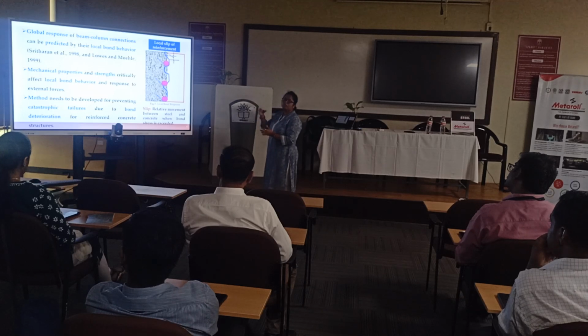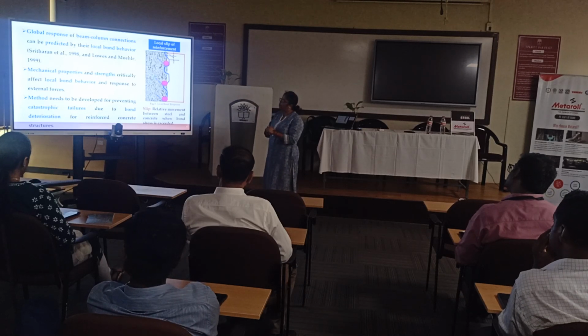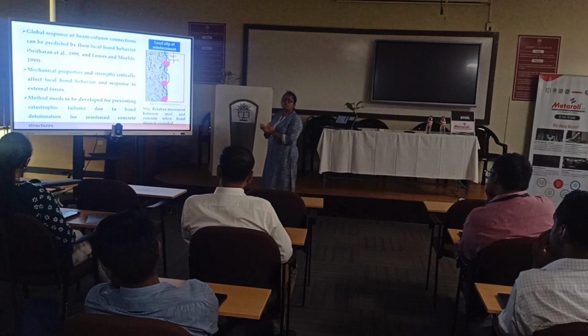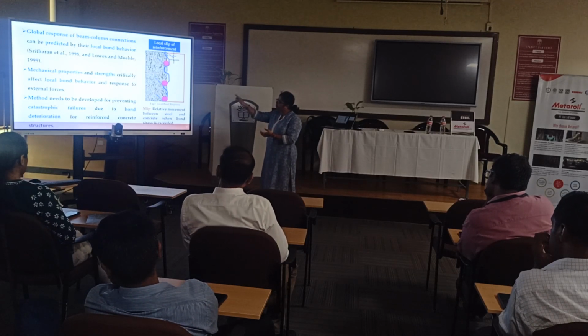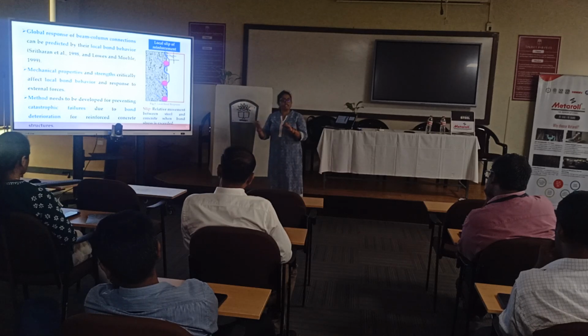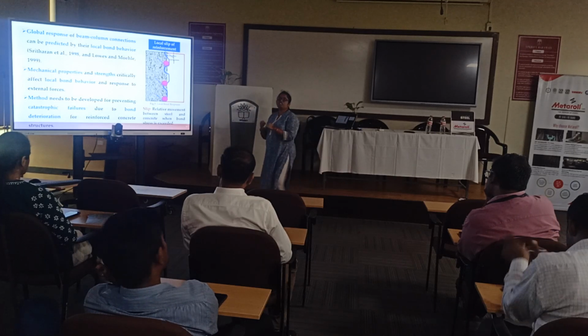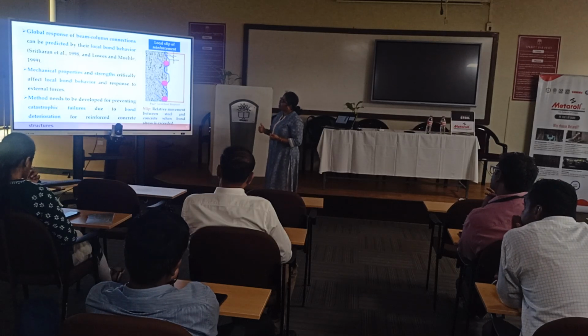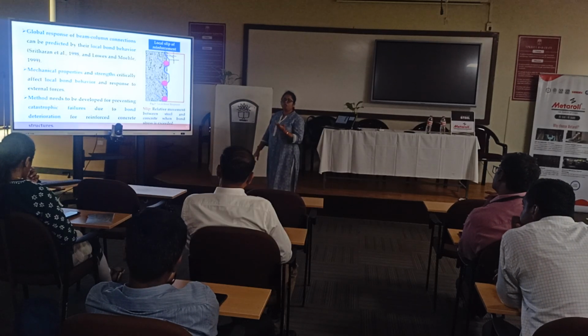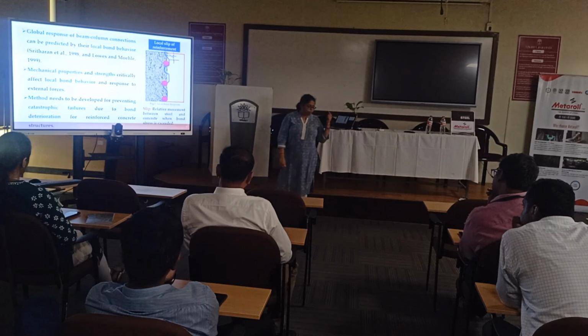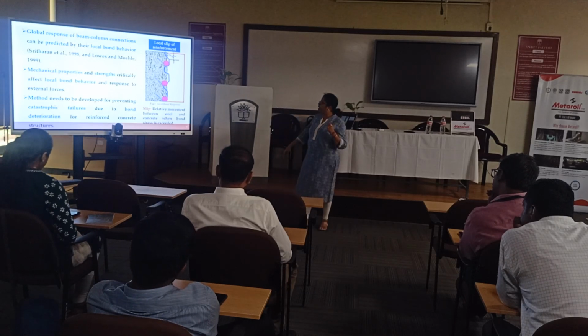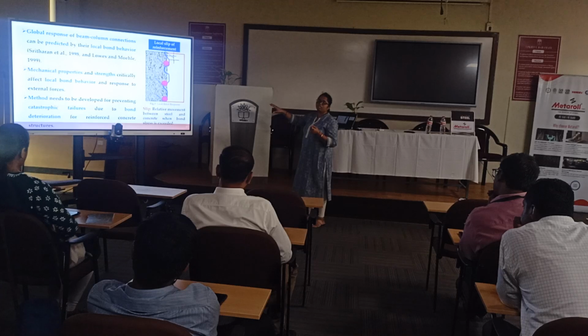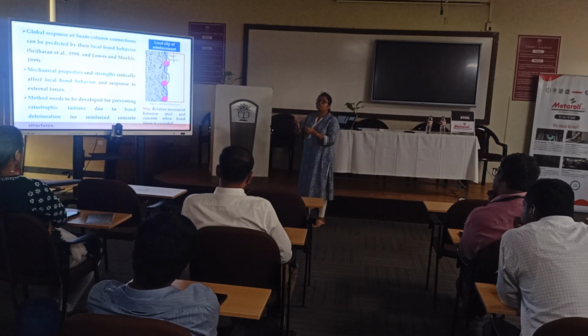Now when the reinforcement is embedded in concrete, it has adhesion. It has chemical adhesion and mechanical interlocking because of the undulations on the steel reinforcement, and a shear bond configuration during the hydration development. Now, when they break, there are two types of bond failure. We call one flexural bond and the other anchorage bond. Most of what we are dealing with in this particular research is the pull-out test, which is called anchorage behavior.